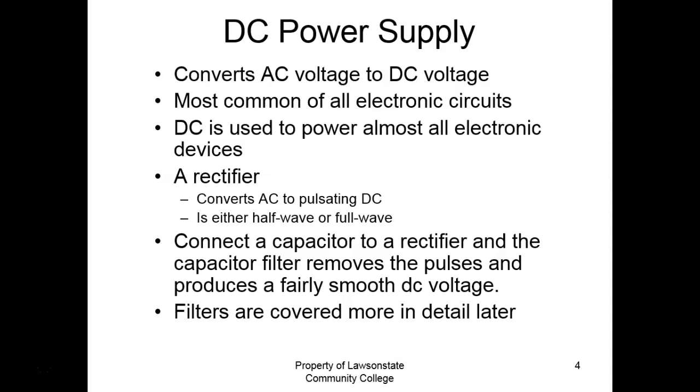A rectifier, this is the actual circuitry that's converting AC into what we call pulsating DC. Then what we're going to have to do is come in and try to filter that out and convert it into what we call unregulated DC.